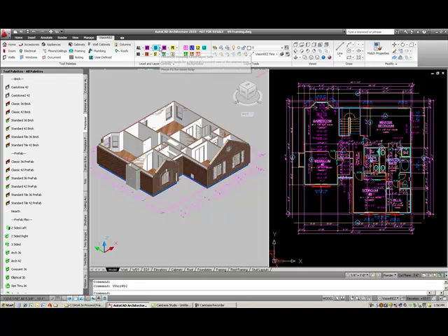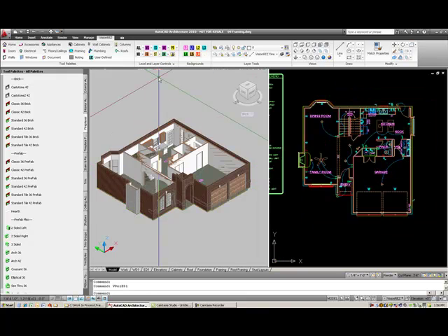If I go to the ED, which stands for electrical drawing, I can select ED1 and it'll turn on the electrical drawing of my first floor. And I have controls to show the working drawing with the electrical. I have a presentation layer set, which just shows my presentation levels. I can show my framing, I can show my studs, and I can show decking. There's also a layer key override.